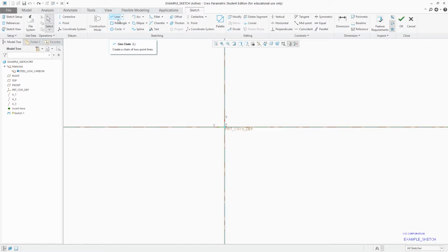Now starting with line first. These are the basic sketching tools, which are mostly used by us, and are among the commonly used tools in the Sketcher module. So in our start line, just click on line, and you do not need to worry like we worry in AutoCAD, where we need to define our first point in terms of X, Y, and Z, and then the second point.